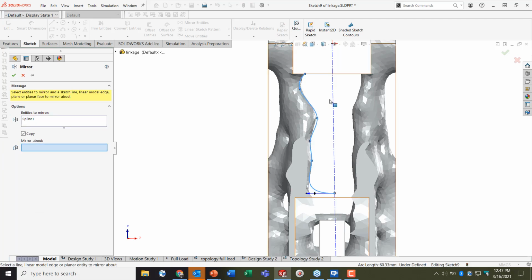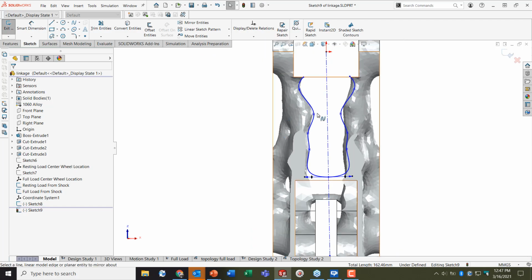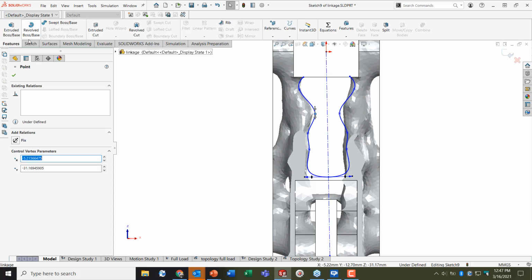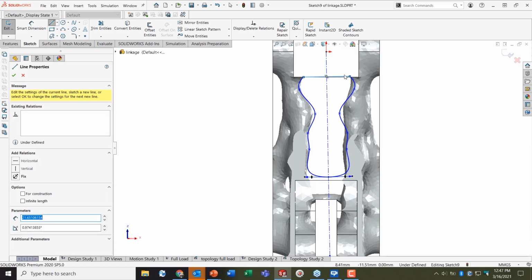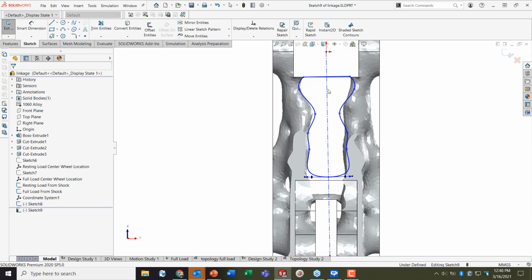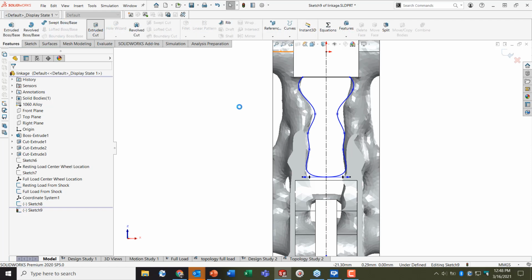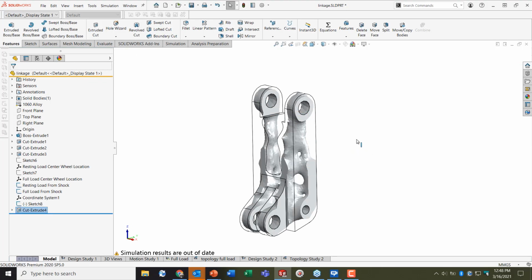So once you have applied the simulation overlay, it's a simple matter of your regular SOLIDWORKS sketching and modeling skills at this point. So now I have a very symmetric profile. And I can go ahead and, let me just close off this shape. And I can go ahead and do a regular extruded cut from here. Similarly, for any cutouts that I do on one side, I'll just use the regular SOLIDWORKS mirror feature for those features in order to make everything nice and symmetrical in my cutouts.